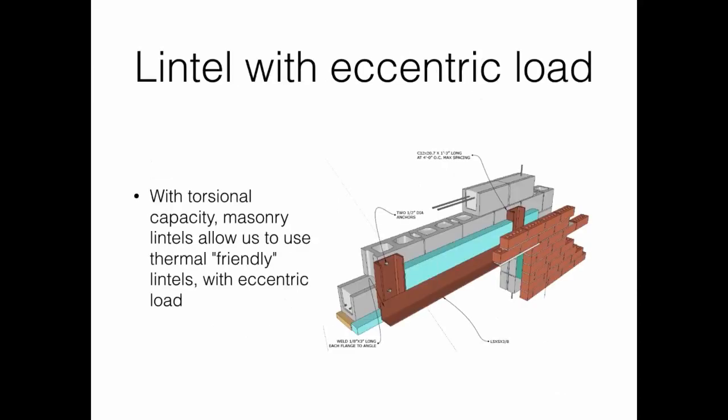All right, so I think we talked about torsional capacity, lintels with that eccentric load. Steel really doesn't work well at all. Masonry is going to work very well. It's going to be very efficient. It's interconnected. I keep saying that, right? It's connected with the wall above it.